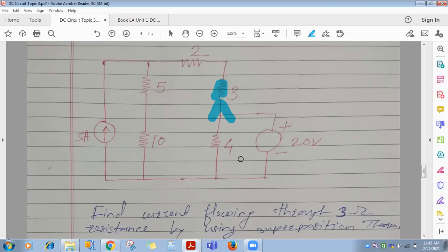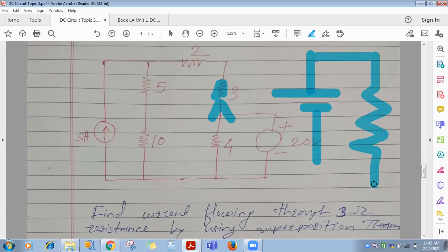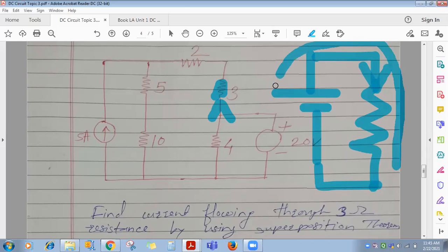The question is, through a resistance, take a simple circuit. Suppose this is the voltage source, and across it you connect one resistance. Now through this resistance R, I am changing the current direction, initially downward and next time upward. Will the voltage-current characteristics of this circuit change if you change the current direction? No, ma'am, only the values will be positive and negative. Right, characteristics will not change. That is called a linear circuit.